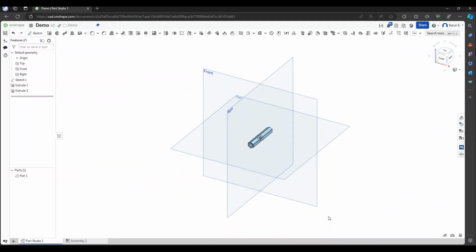So now that we have the standoff done, we're like, oh, that's great. We have a standoff, but wait, we still have to make that 1-inch ball bearing that I didn't talk about earlier. And so to do that, we want to actually make that bearing before we make this part. So we essentially need to go back in time. And thankfully, there's a tool for this in Onshape called the rollback bar. So here we can actually drag this before certain actions were taken, and we can essentially travel back in time.